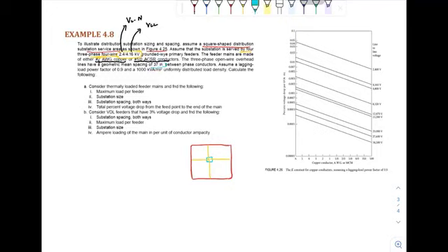This is the spacing between phase conductors, 37 inches, and this is the load density. So you can add the word increasing over here. The solution is for uniformly increasing load density. Now we have to compute using the two assumptions which we have discussed earlier. First of all, we have to consider thermally loaded feeders, and then we have to consider voltage drop limited feeders. Using these two assumptions, we need to compute the substation size, the maximum load per feeder, and the spacing of the substation.